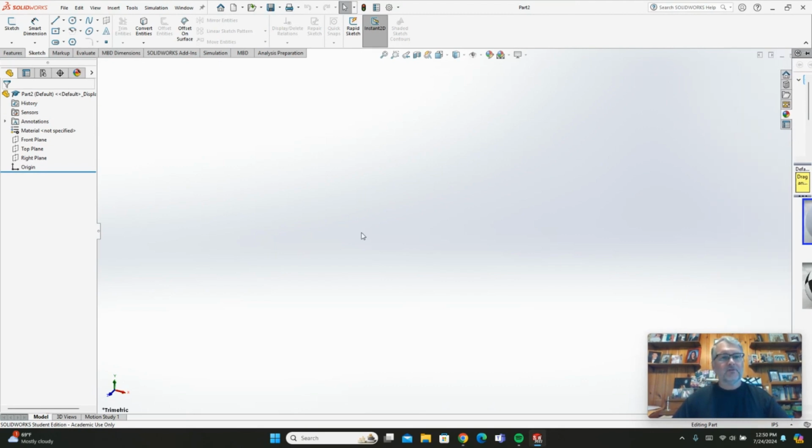All right, so let's just do some real elementary things here to show you some of the menu items. Whenever you start a sketch, you have to pick a plane. You're required to sketch on a plane. Now, it's very important what plane you pick when you start a drawing. You pick your plane based on maybe the easiest way to draw it. If you're drawing something that is all going to be from the front and working backwards or frontwards, then we would pick the front plane, and same thing for the top and the right.